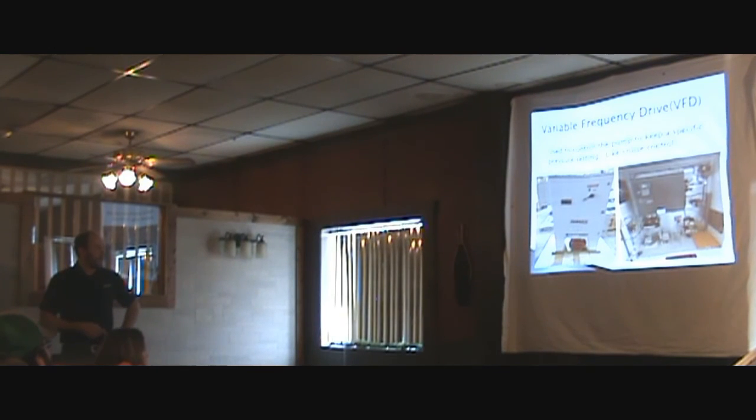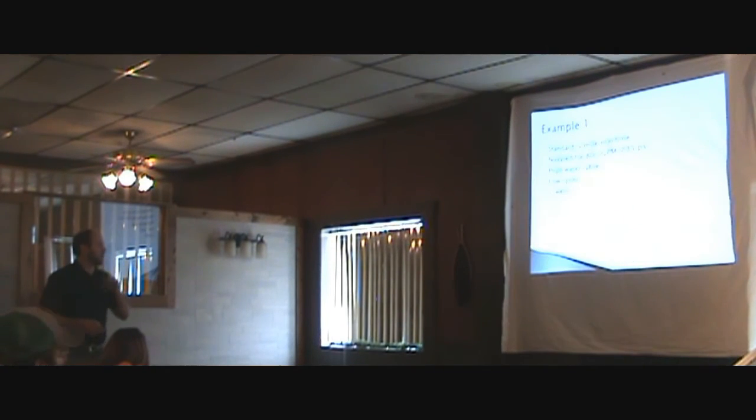This one here actually has a rotophase on it. That's just a phase conversion panel. This one is converting single phase to 3-phase for the pump and single phase to 3-phase for the pivot. This doesn't have to have a rotophase on it. That's just if you need to control them both.